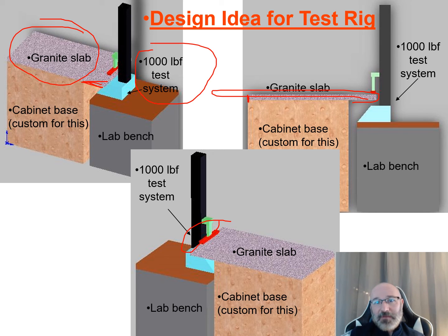But we'll put in a safety factor as well. So maybe we'll go up to 500 or 600 pounds with a safety factor in that. But this is considering static loading. What if somebody jumps on the edge of the counter? And you've got that impact loading. So all of those types of things might be a little bit more FEA that you'd want to do